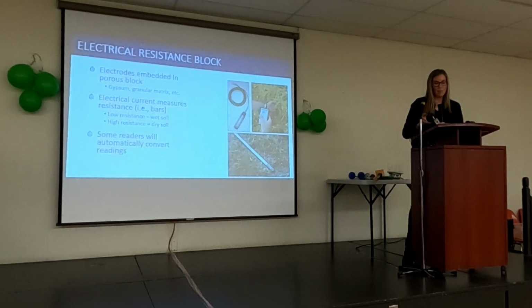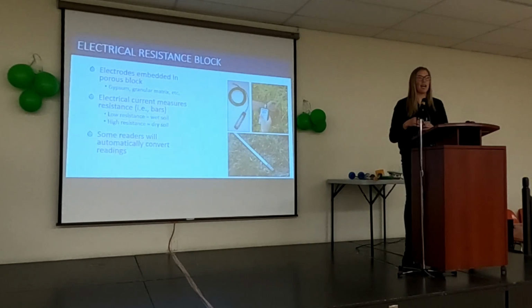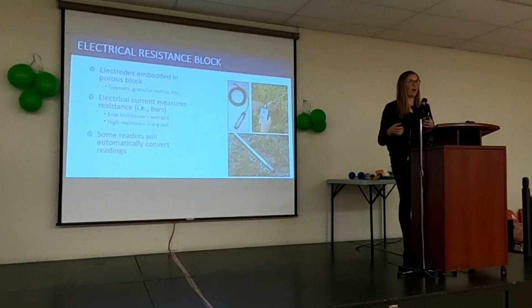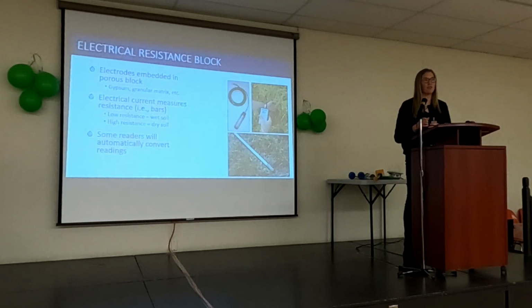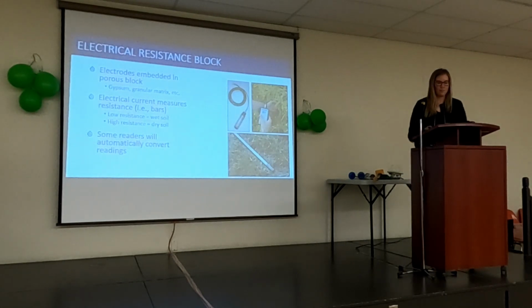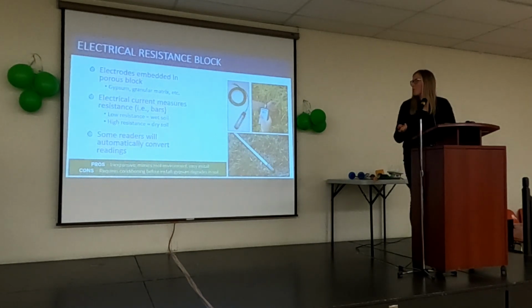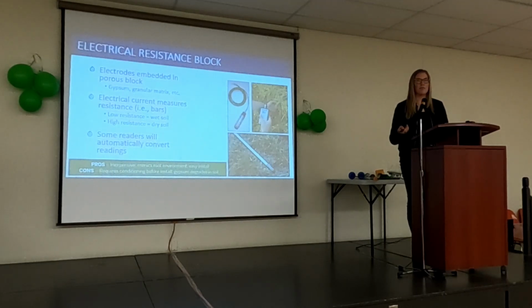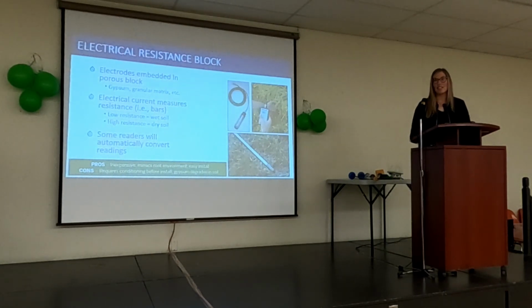So these can be read manually with a reader such as this, or else they are suitable to set up to a data logging system. I'm not super familiar with data loggers, but you can basically hook them up and then have that data logger feeding you the output every hour or something like that to reduce the need to go out to the field. And some of the pros, this is also pretty inexpensive. The probes themselves, I believe, are about $150 to construct, and then the reader itself is a few $100s. They're also very easy to install, and like I mentioned, suitable for data loggers.